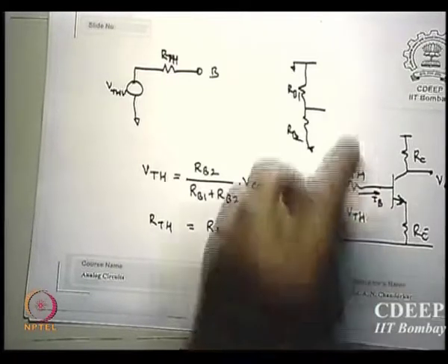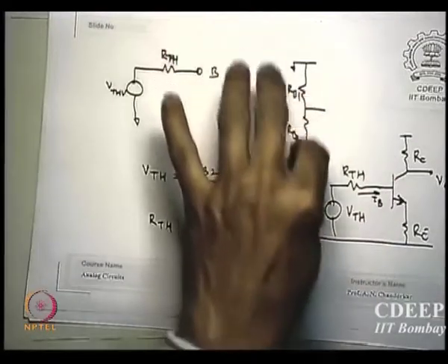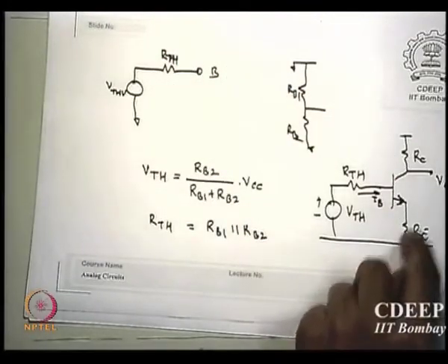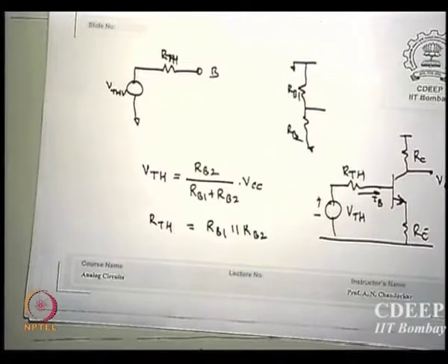Now in this circuit, if I am given RB1, RB2, RE and RC, then the values of resistances are given and I can find the operating point. If I am given an operating point, then I will not be given RC and RB, and I will have to evaluate them by the inverse operation, is that correct? What is the difference between analysis and design?